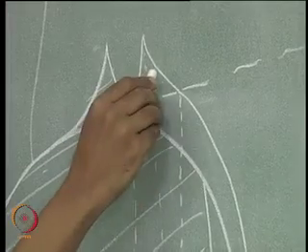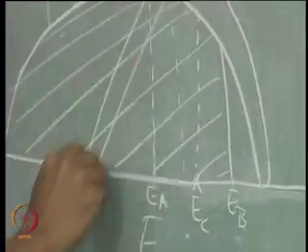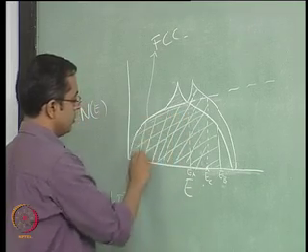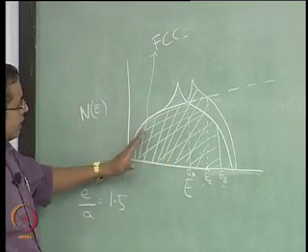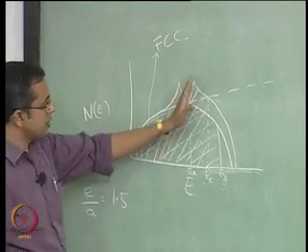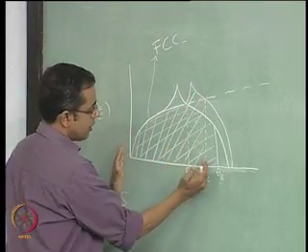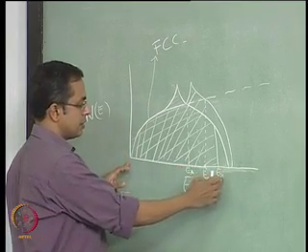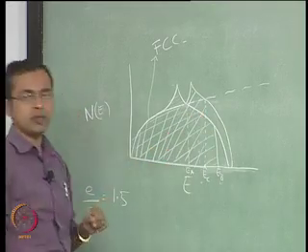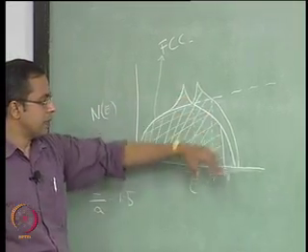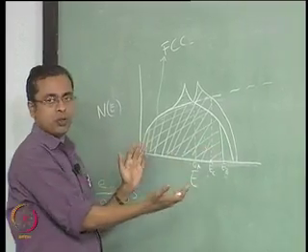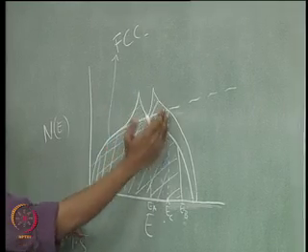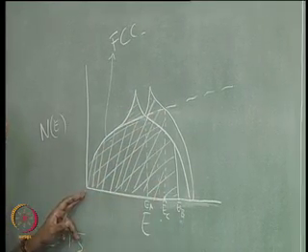So in the BCC structure you are able to accommodate more electrons in a smaller energy window relative to the FCC structure, simply because of where the turnoff is occurring, where it is beginning to change shape. Okay, so it is simply a matter of area under the curve, if you want to look at it that way. The same area in this curve can be accommodated in a smaller energy window.